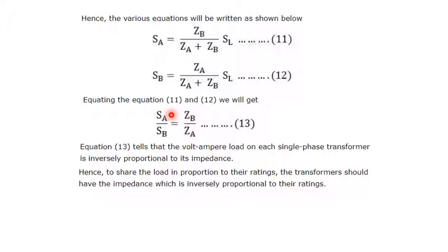Hence, to share the load in proportion to their rating, the transformers should have impedance which is inversely proportional to their rating. So this is one more condition, and it should be fulfilled. Then only we go for the parallel operation of transformers.